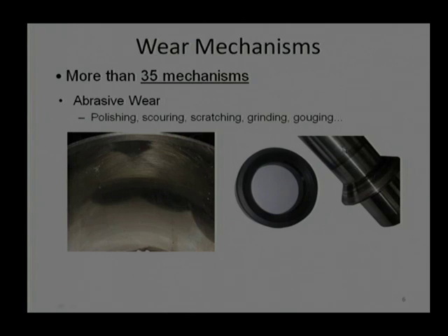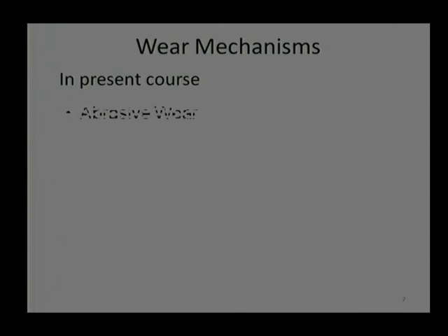Now, if somebody by mistake thinks, oh, this surface is getting dirty, some black marks are there, I want to polish at every new operation and get good performance, then he will be mistaken. This layer has been deposited intentionally. It has the basic physics behind it, and if somebody without understanding it tries to remove it, thinking this is a dirty surface, it should be cleaned before assembly, then he will cause unnecessary failure of the component, unnecessary wear of the surface, and higher power loss. So, that is polishing wear, right.